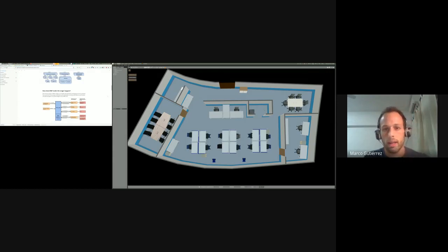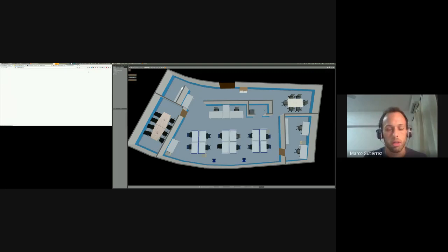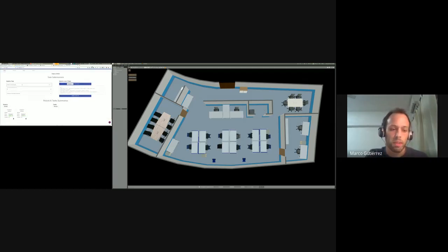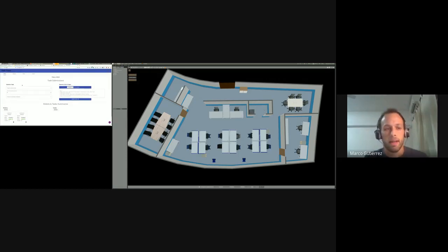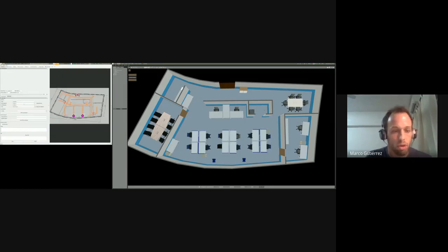And the way to do that is through the web. So if you're using the source version, I think it's port 5000. Yeah, it should be. So there's the web panel, which allows you to submit the tasks. And as I said, it's a bit of a hybrid right now. So the lanes and the traffic monitoring are still in the RViz. If you install the version from ROS Foxy, you will see something like this. Still here, the RMF panel, but it's just not in the configuration anymore. So you can also submit the tasks through the RMF panel here.